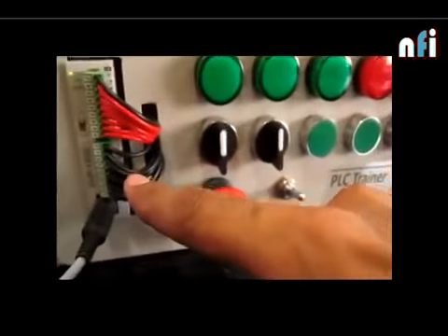And this is a 2 position switch. In between it is not giving any signal, and if I go here, it will turn on the input X0. You can see here, it is giving X0 input, and at this side it is giving X1. Similarly, a second toggle is giving X2 and X3, and these are another 2 push buttons, X4, X5, X6 and X7. So from X0 to X7 we have 8 inputs and a total of 6 outputs. So this is the brief about our PLC trainer.